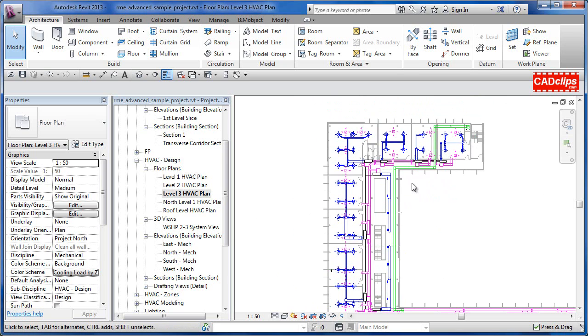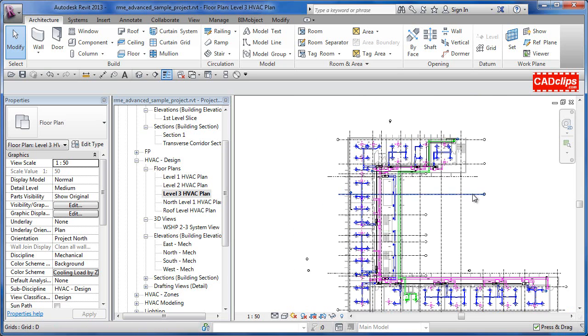So we just want to make sure when we have our grid lines that the vertical part actually comes up to the highest level. If you go up to the roof level here and this grid line hasn't literally been pulled up to that level, it won't show up, because this grid line has to cut the level line in order to show up in the floor plan based on that level.